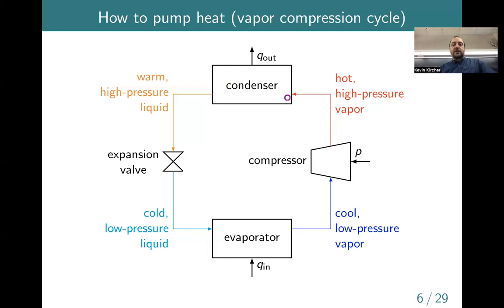That goes into this heat exchanger called a condenser, because we take vapor or gas and we basically condense it into a liquid state in that device. And then that gives a heat transfer output. So you could think of the refrigerant in here and then maybe a stream of air from a supply air duct, for example, out here. And so there'd be cool air coming in. It would do heat exchange essentially with the hot vapor in here, and it would cool down the vapor, and then the vapor would do a phase change. It would begin to condense.